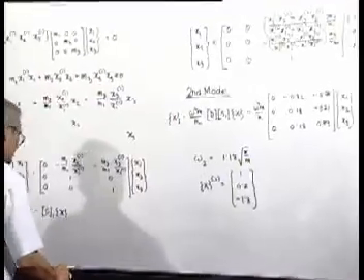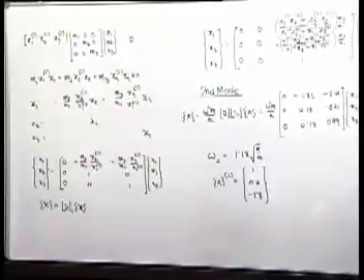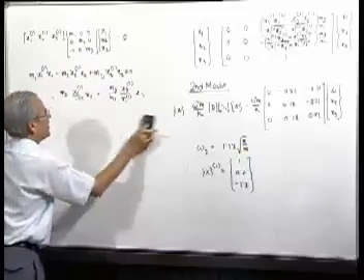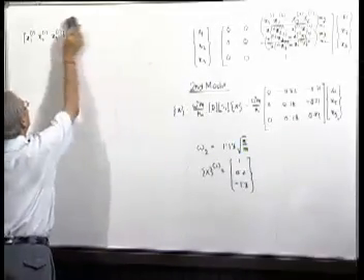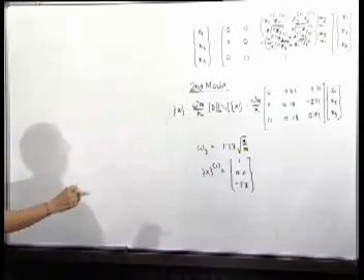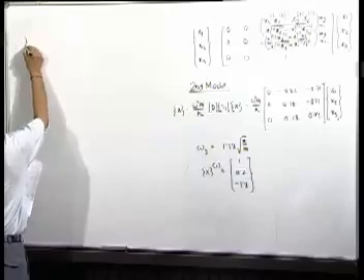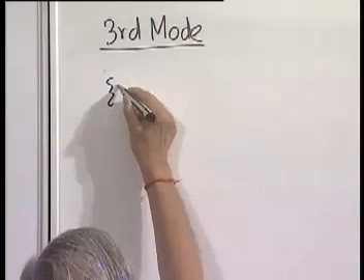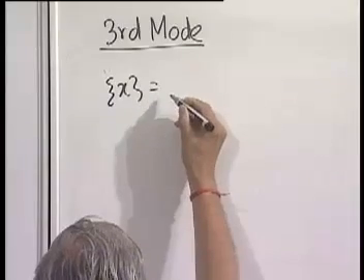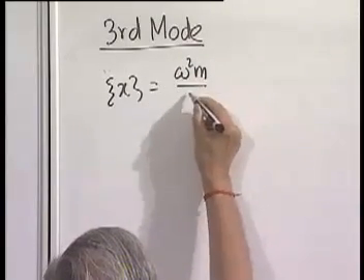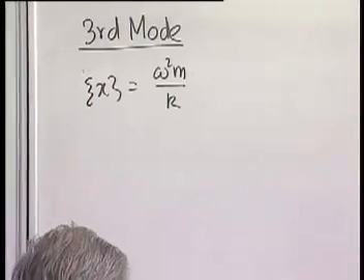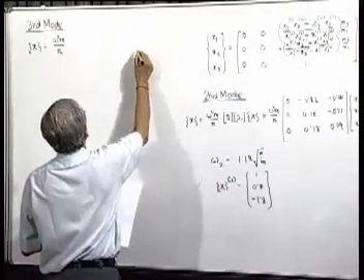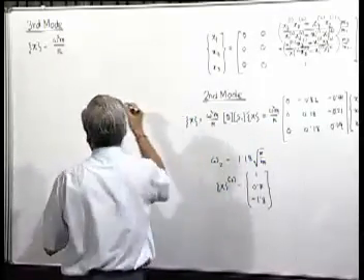If we multiply that by D, the equation we will get for the third mode is the sweeping matrix to sweep out both the first and second mode, and your third mode equation becomes this matrix as the sweeping matrix. Directly you can write.